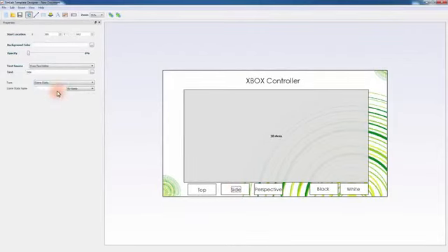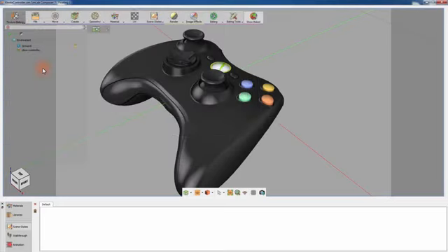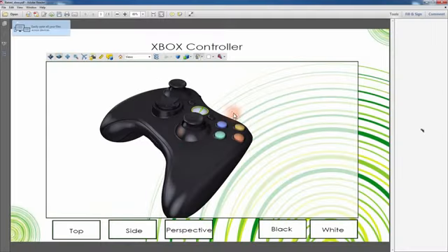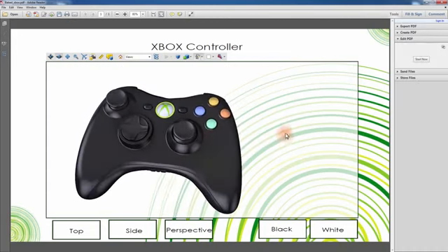An additional SimLab Composer feature that complements the 3D PDF is texture baking. Texture baking is a process that calculates the values of light and shadows along with the materials in the scene, and converts them to a texture map that mimics the behavior of a rendered image when applied to the model. This allows the user to view the model in a rendered quality from several angles without the need to render each angle separately. You can export models that have baked textures applied to them in the same fashion as regular models. More explanations and tutorials on texture baking can be found on SimLab Soft's official website.